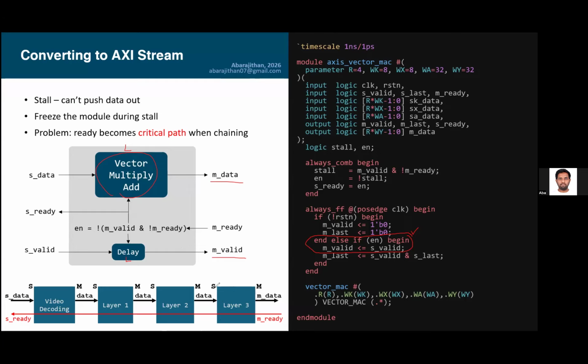It depends on your design. If your design has a fixed latency, then I would say you can do this because it's very easy to do. And I don't think you will have any performance impact, because the tool can move the registers. If you enable retiming in the tool, then the tool can actually move the registers inside. I think doing it like this will keep your code clean. It depends on what kind of stuff you are doing.